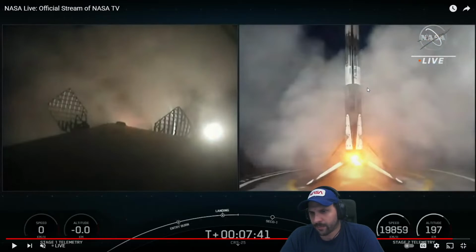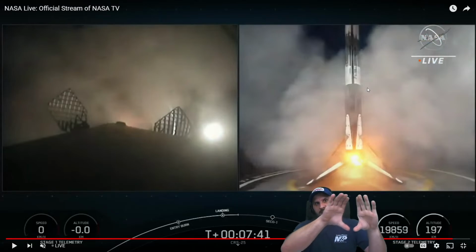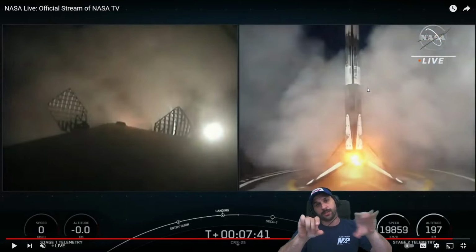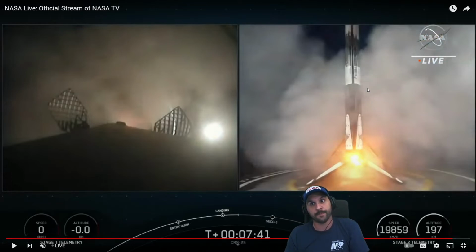Is that like an afterburner on a jet? Chuck, no, not really. What a jet engine does is it has a compressor at the front, right? What's called an axial compressor. So it's sucking in air, and then from the compressor it goes into a funnel, and then it pressurizes that air, because the same amount of air flowing in going into a smaller area is going to pressurize the air, right? And where that air pressurizes, from there it goes into what's called a combustor.